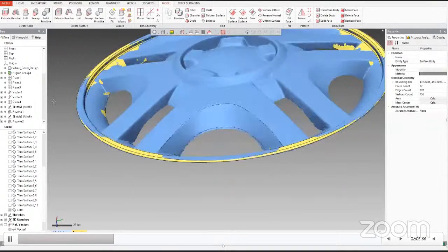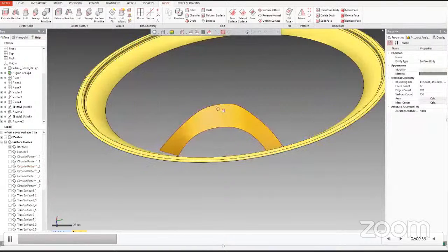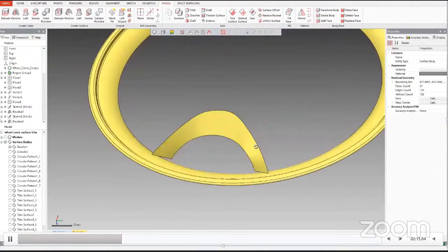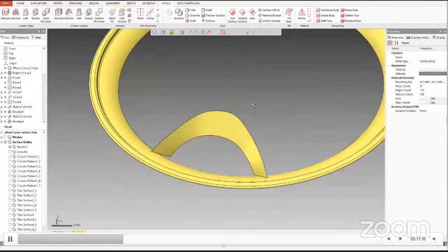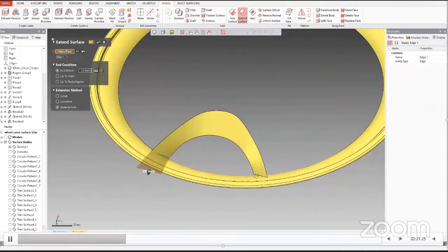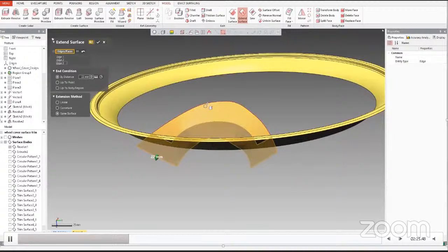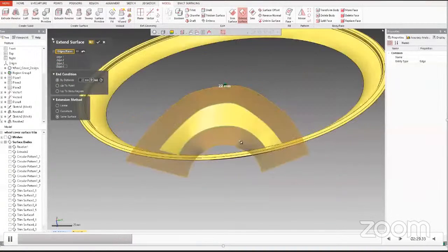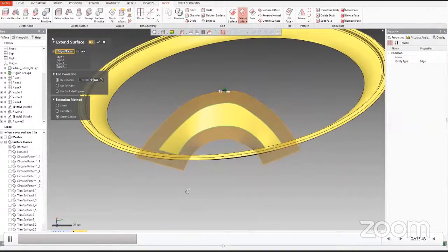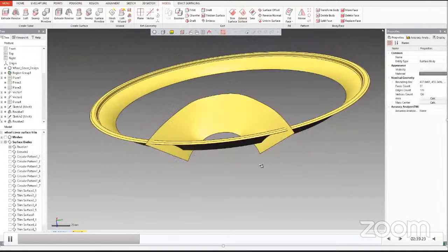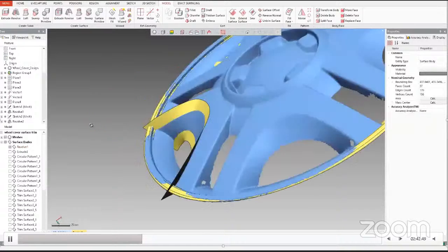So we have just created this surface. It also shows the dark yellow color. We will convert the direction, so we move the surface downward. We use the extend command to extend the legs of this surface, also extend the height of it, and also at the bottom. We are extending these just to use the trimming commands, so the surfaces are linked to each other properly.